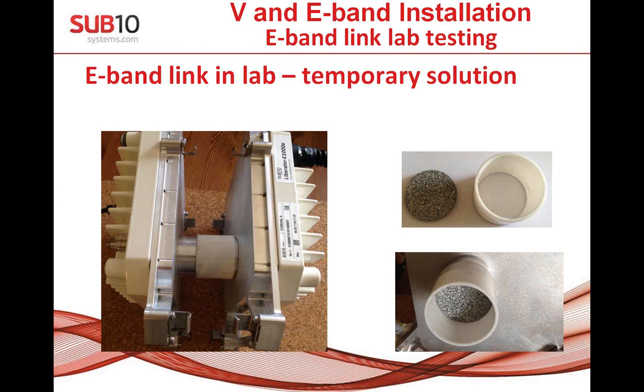On the new system you have a label here, a warning that if you take it out, you void the warranty. But remember, do not remove it, because otherwise you are making an easy way for water to go inside the terminal. If a small amount of water goes in, the first place it goes is the RJ45 connector, where power is also going in, and you will have water on power which is plus 53 volts DC, and the copper on these connectors will be destroyed very soon, and your system will not be functional.